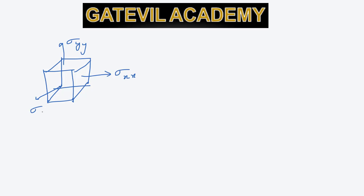If there is a cube which is acted upon by 3D stresses, now there will be some stress sigma xx, some stress sigma yy, and some stress sigma zz. Corresponding to these, there will be strains epsilon xx along the x direction, epsilon yy along the y direction, and epsilon zz along the z direction.